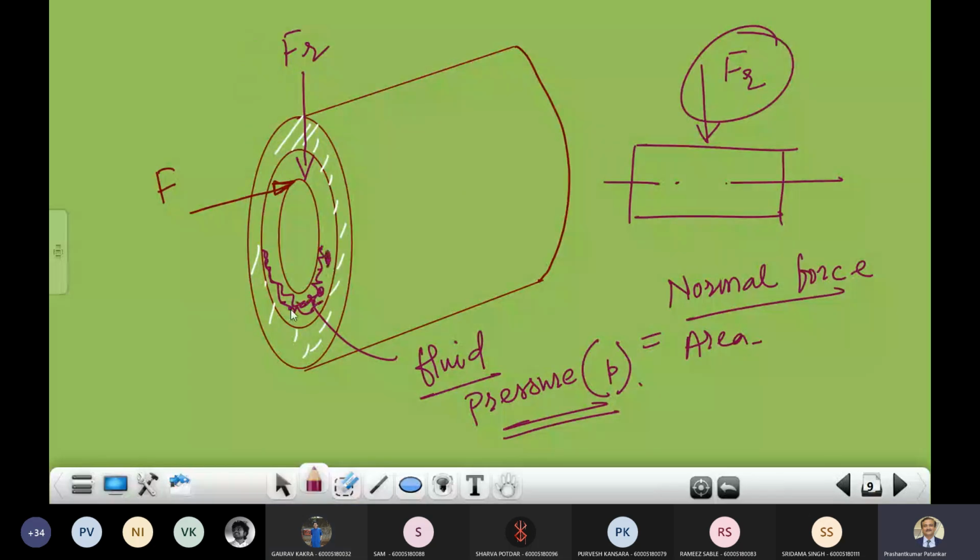Here, though we are saying that we have the clearance, let me tell you one thing. This particular clearance is always in microns. Just to make you understand, in all these figures you will find a huge clearance, but in real life situations that clearance is in microns. For example, if I write the diameter of your shaft as 25 plus minus 0.5 millimeter, in this particular case 25 is my basic size, and 25.5 and 24.5 are your upper limit and lower limit.